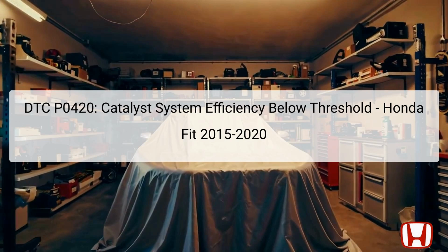The Honda Fit, model years 2015 to 2020, can sometimes display Diagnostic Trouble Code P0420, which signifies that the catalyst system efficiency is below the acceptable threshold. Catalytic converters play a vital role in reducing harmful emissions by converting toxic gases into less harmful substances. In this case, when the readings from the onboard diagnostic system indicate that the efficiency of the catalytic converter is compromised, this code is triggered.